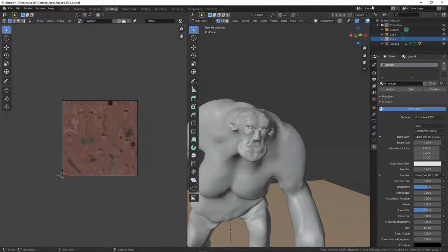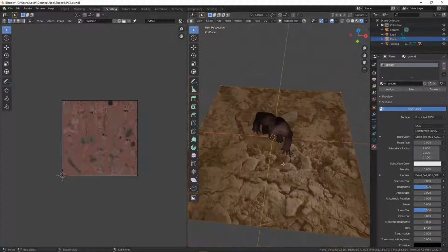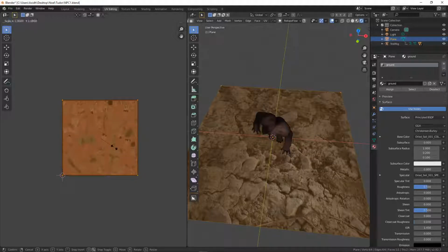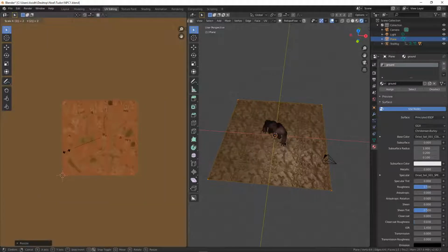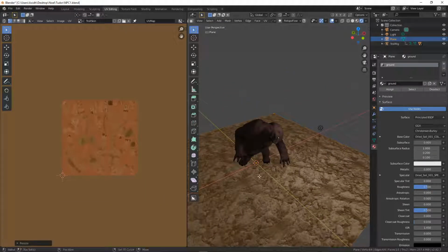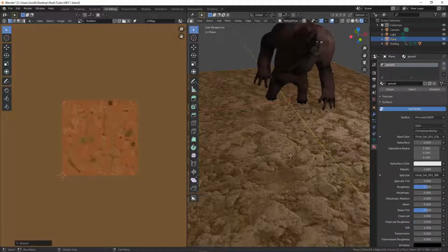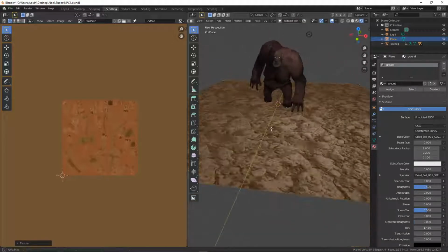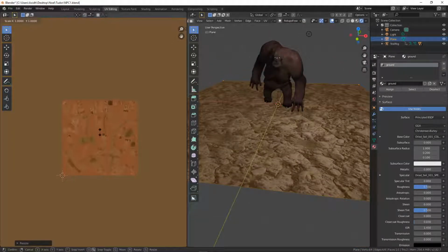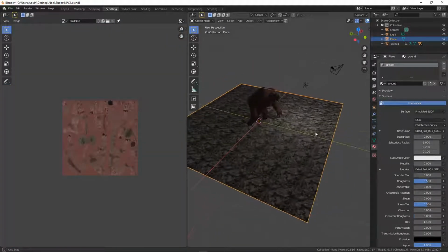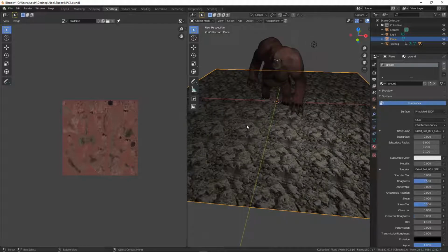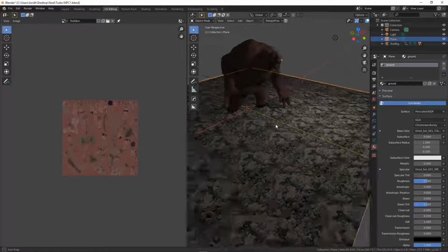So what am I going to do? I'm going to just scale it on UVs. So I'll select all my verts here, all 4 of them. I can go scale 2, that's twice as big. I can go scale 2 again. Now we're starting to see a repeat pattern here, which is not great. And then we'll scale it one more time. Scale 2. Now, that's not terribly good because we can see the repeat pattern in it.